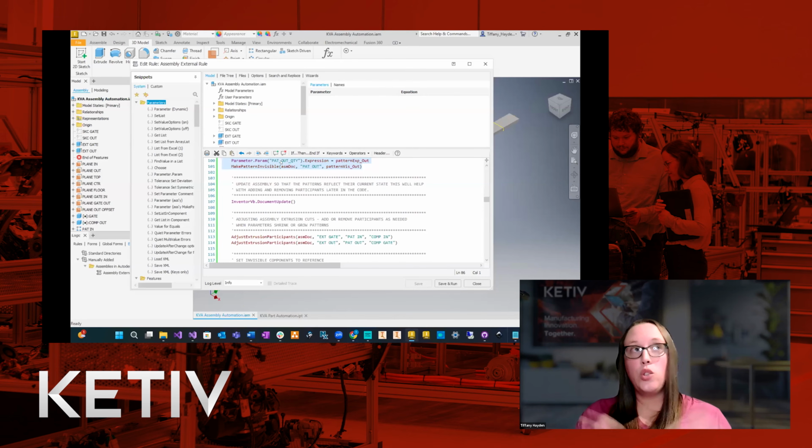So let's say you change the length and it went from having 8 elements to 6 elements. Well, if you don't do an assembly update, it still thinks that there's 8 elements. So when you're doing an extrusion and looking at patterns to determine what the last element in the pattern is, make sure to do that assembly update right before you start messing with the extrusion, or you're going to add and remove things that aren't accurate.